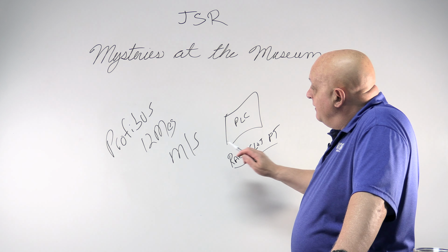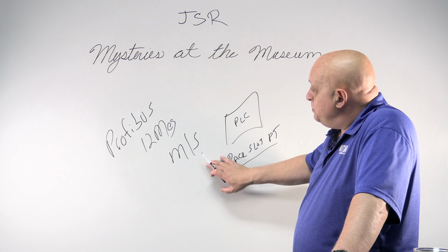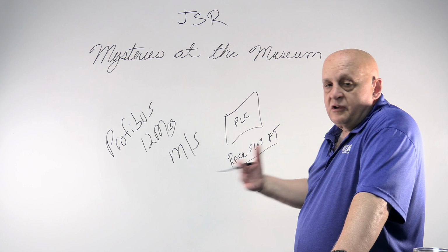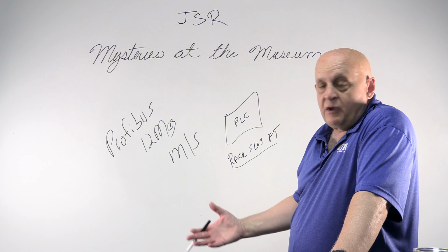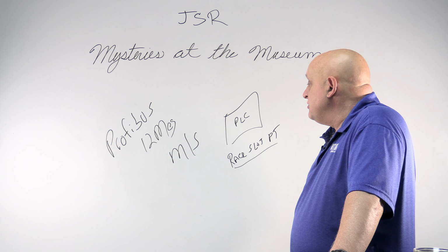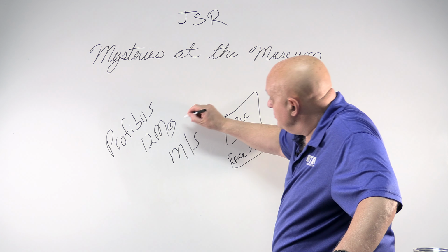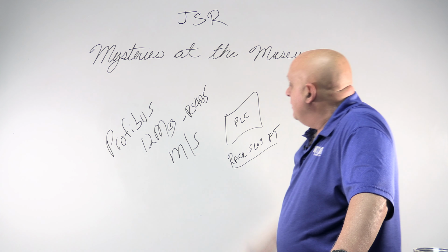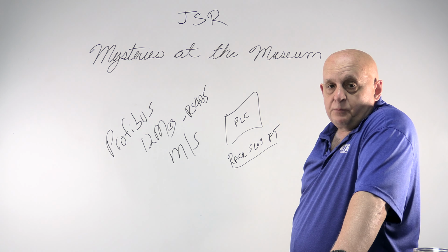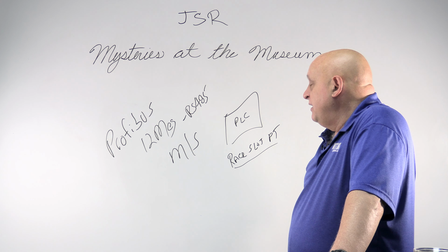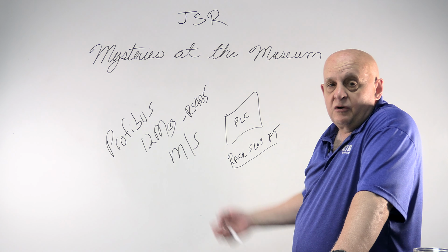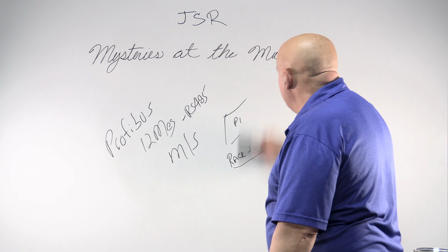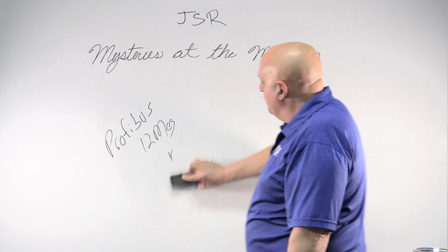And just like DeviceNet, you need to have a chip inside of it to do that 12 meg. Typically, DeviceNet uses CAN as a basis. This uses serial, but a special serial. So this is actually RS-485, with special chips to make it go that fast. So you needed to buy special hardware to get on both Profibus or DeviceNet. Those are both sensor networks.